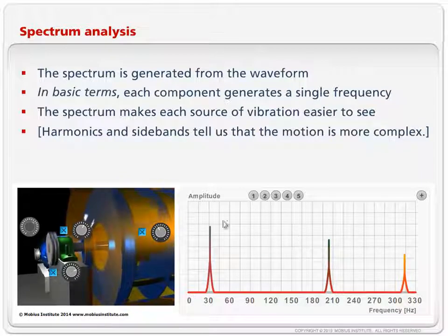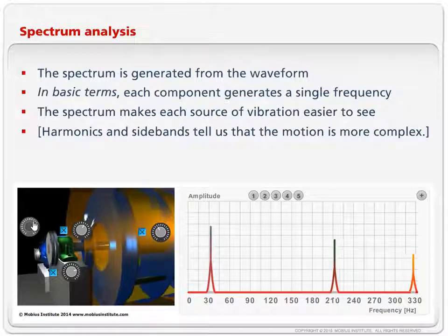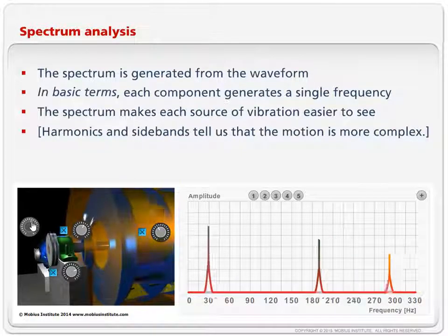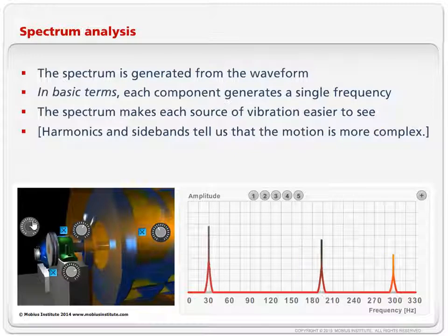Either way, this is basically what we end up with, and just to keep it simple, I'm just going to line that, just get that lined up. Anyway, the reason I'm trying to do that, and not doing it very well, is that what we've shown here is this is the frequency, and I'm simulating this as if right now, that's what I was just trying to do with the knob, make it vibrate at 30 Hertz, because I've got 10 blades, so therefore the vibration from the fan would be at 300 Hertz.